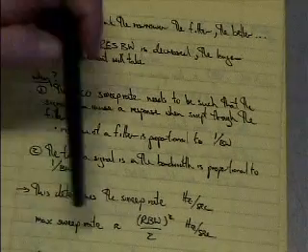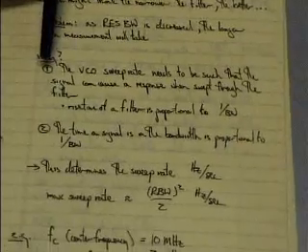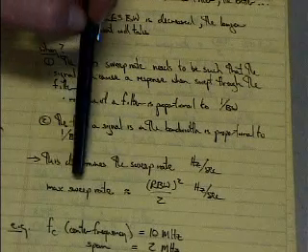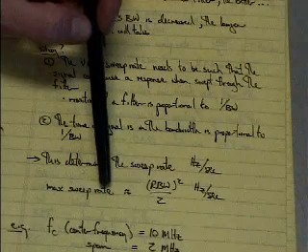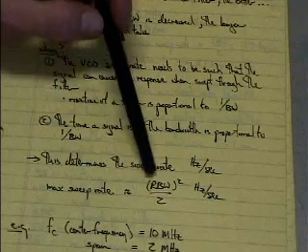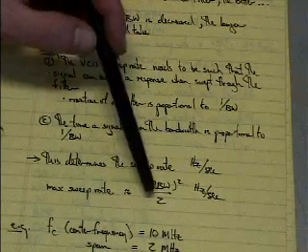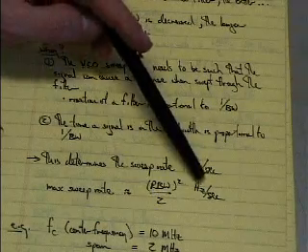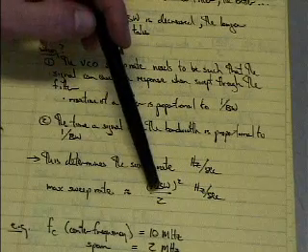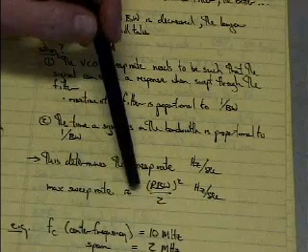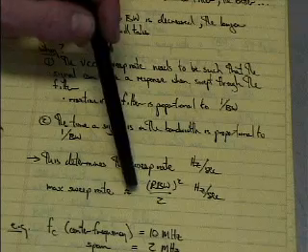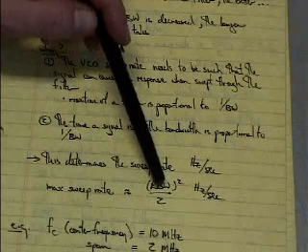And here's a nice little approximation that we're going to be using: the maximum sweep rate, that is, how fast we can sweep our VCO, is going to be the res bandwidth squared divided by 2, and that's going to be in hertz per second. So I can only sweep across the spectrum analyzer so many hertz per second, determined by my res bandwidth.